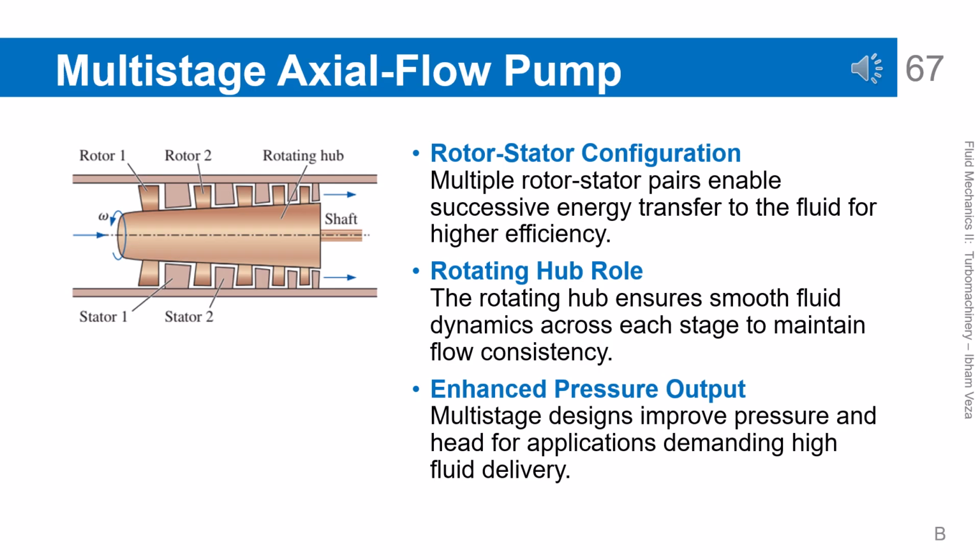Multi-stage axial flow pump uses multiple rotor-stator pairs to increase fluid energy step by step, so that the total pressure can be raised without overstressing a single stage. Each stage adds kinetic energy and pressure to the flow, making the overall system more efficient for high-pressure applications.